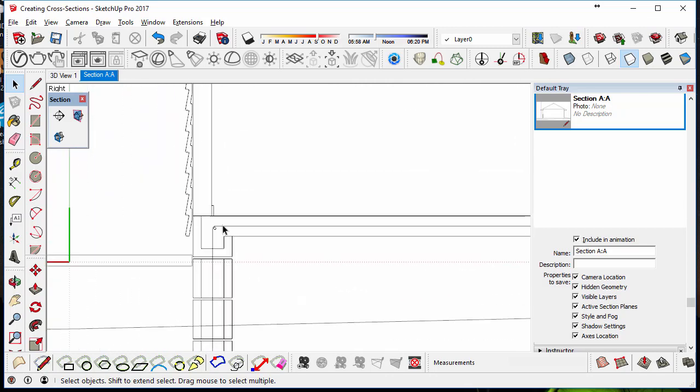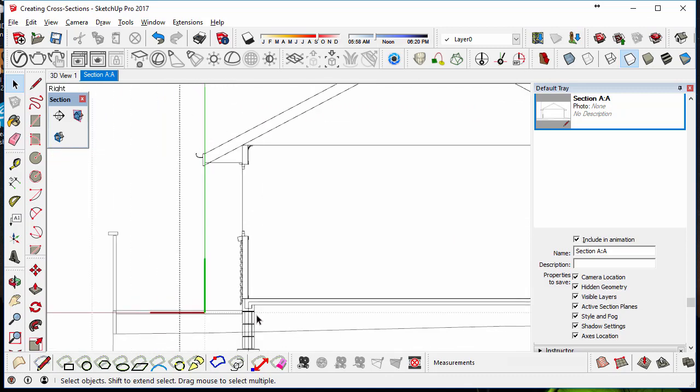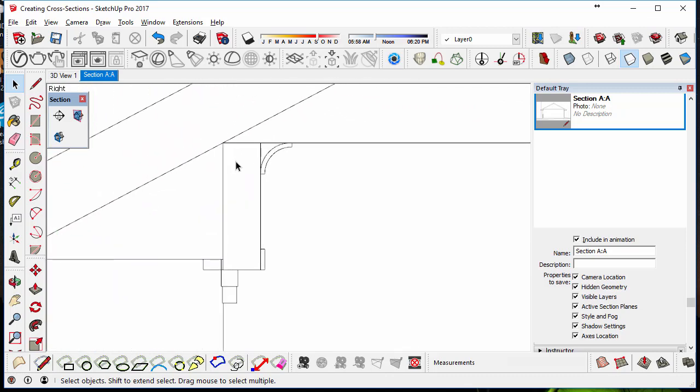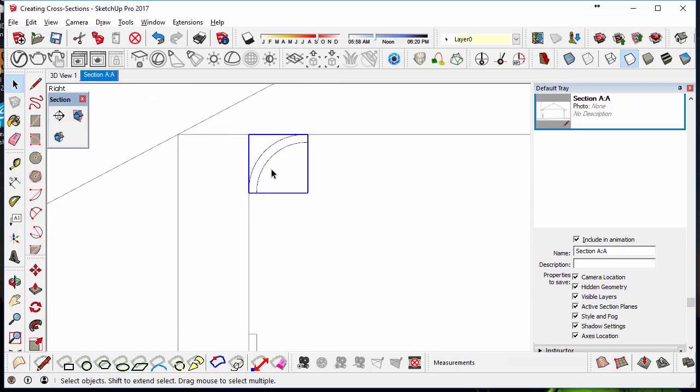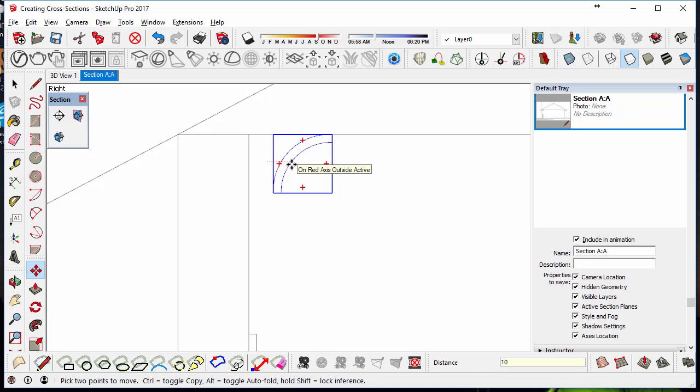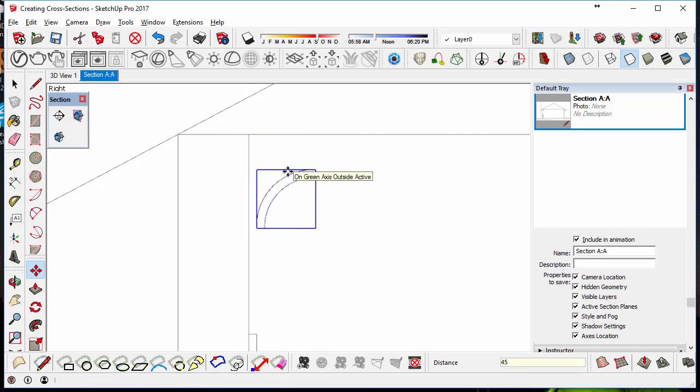Okay, so let's say you wanted to create a top plate and create your own components. So if we go here, I could just select the roof, and I'm just going to go down to the curve in there and get that component and just move it away from the wall 10, because in the 3D model I just put it straight on the wall, I didn't allow for any jib. So then from the top of the jib here I'm going to come down, on top of the framing, let's say 45.